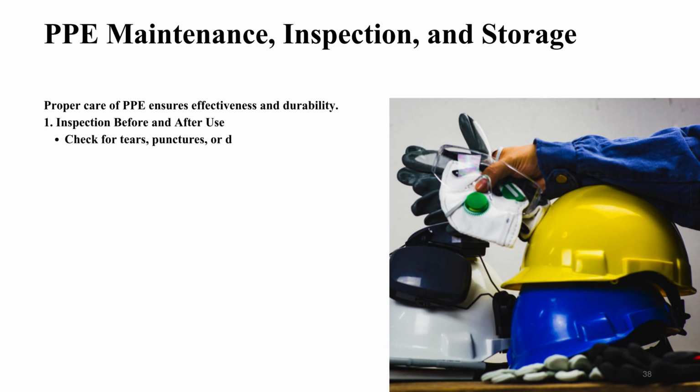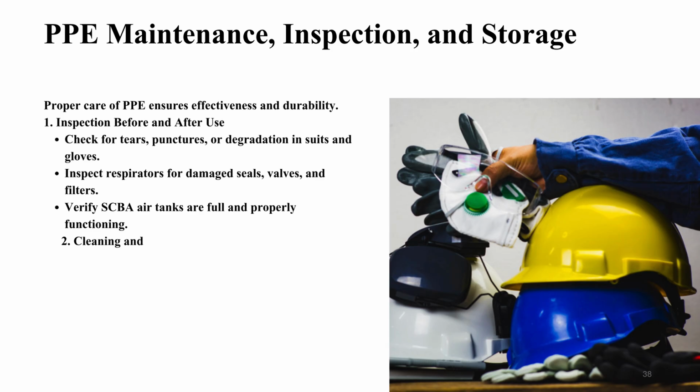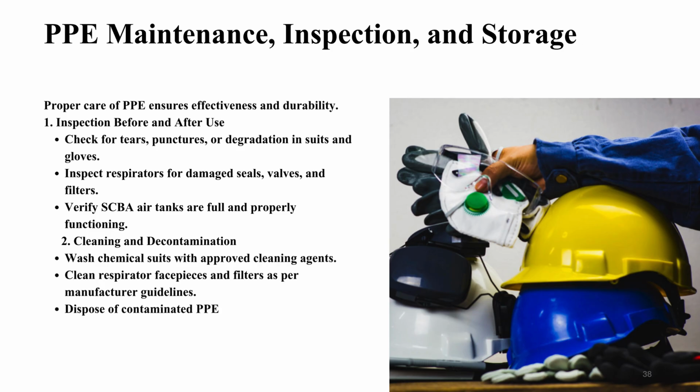PPE maintenance, inspection, and storage. Proper care of PPE ensures effectiveness and durability. 1. Inspection. Before and after use, check for tears, punctures, or degradation in suits and gloves. Inspect respirators for damaged seals, valves, and filters. Verify SCBA air tanks are full and properly functioning.